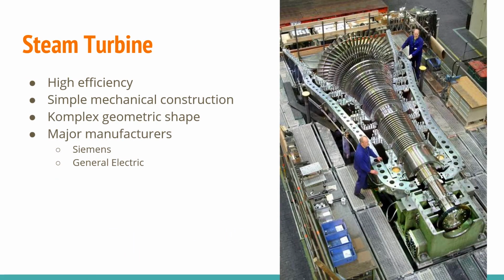Now look into this steam turbine. Here you see a steam turbine, and you always find this shape, small to big. Then you know somewhere here the pressurized steam is entering the system and is expanding all the way out here. And here it is really hot. That's the hot place, and up there is the cold place. And because the steam is expanding over this path, the wheels and shovels get wider and wider.